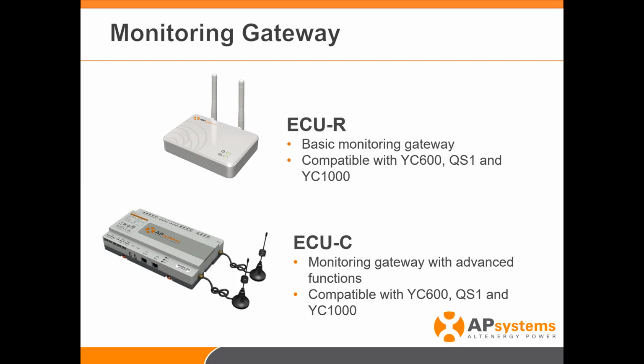It's going to go, are you there? And it's not going to hear anything. At the 10-minute mark, it's going to say, are you there? And it's not going to hear anything. Then at the 15-minute mark, you've already installed your first inverter. The inverter's on the roof. You plug in your first panel, the first DC connection. Remember, like I said, you're going to get that red dot and then 3 blasts of green.